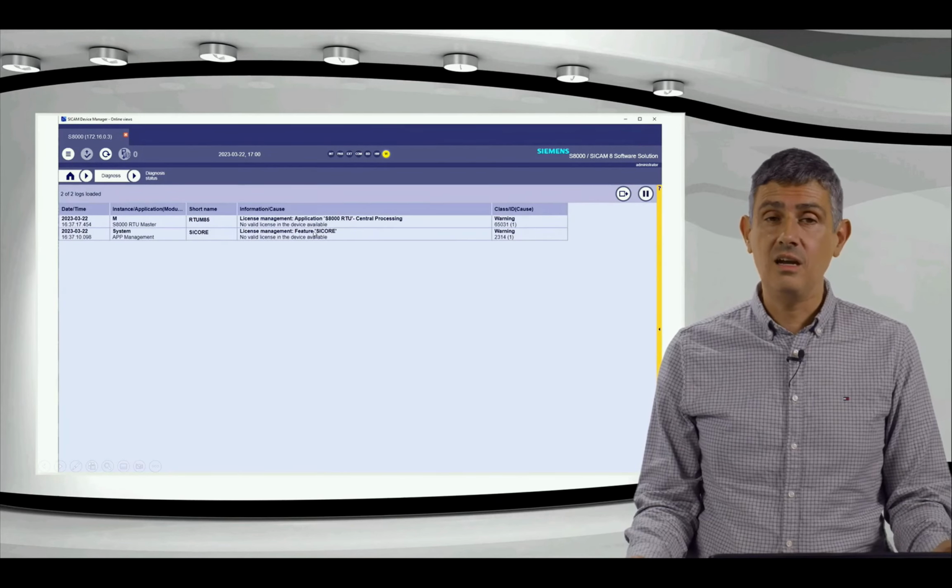and we will navigate further here to the tile definition. And we will add one new line here, which we will call Sicam HMI maybe, and we'll select the position that we selected for startup 1. And most important of all, as layout, we say Sicam HMI. That's it, that's all. After that, we can easily just upload this configuration in the S8000.